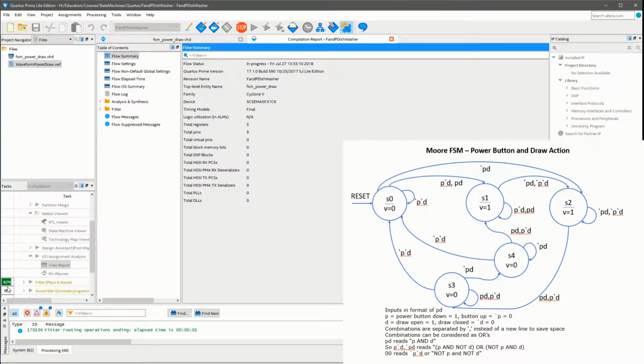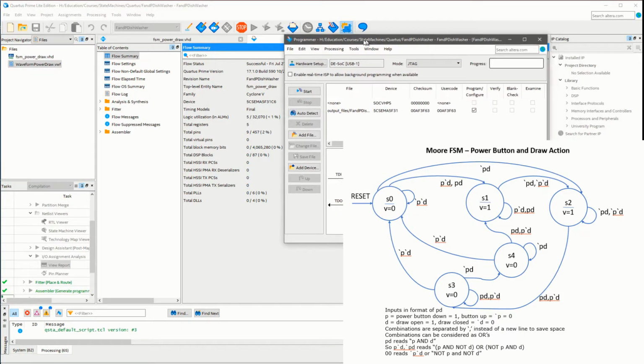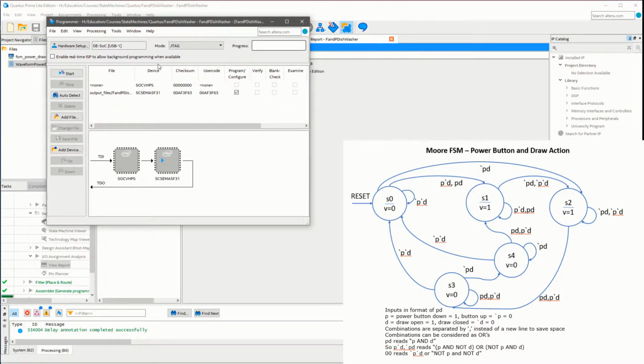We're almost finished. So while we're compiling, I'll get my pin planner open. Almost there. I could open it now actually. Here's our pin planner. And see, I've selected my DE1 SoC. And we've completely finished. We've got 12 warnings. They can be explained, but won't go through that. So right now, let's go and see our FPGA device.